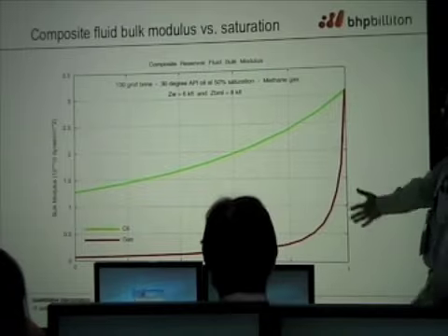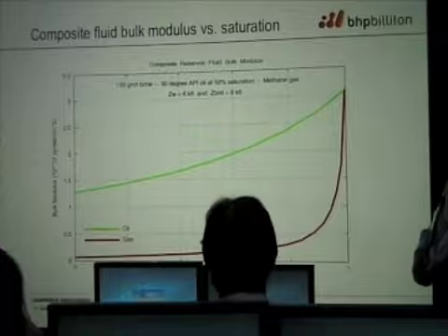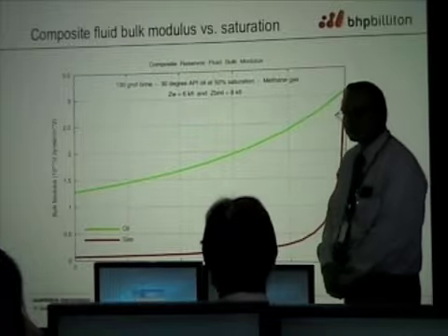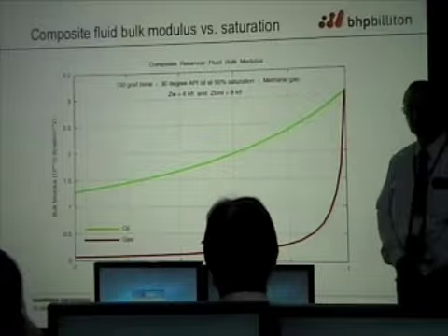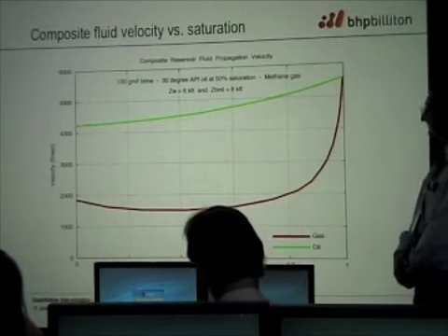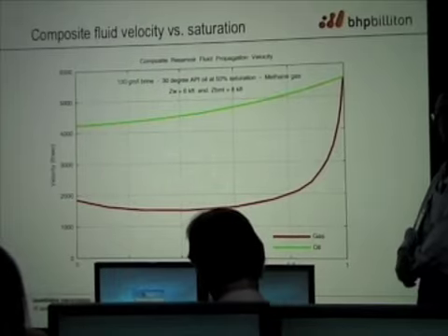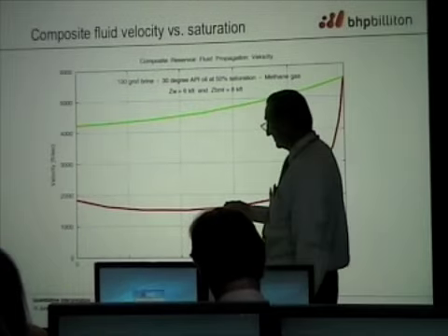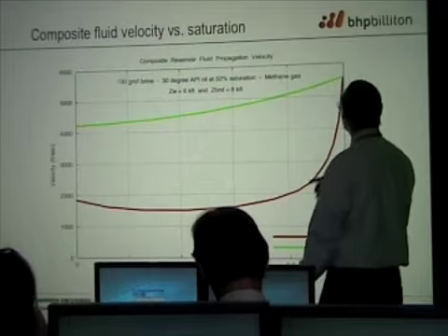Well, gee, this is fluid, right? So composite fluid though it may be, we've got the bulk modulus, we've got the density, we can calculate the velocity. Rho Vp squared is equal to K for a fluid, right? So we can calculate the velocity. Let's look at what the velocity looks like. There it is. You believe this? The velocity at these intermediate concentrations, lots of them, is lower than the velocity at either endpoint.